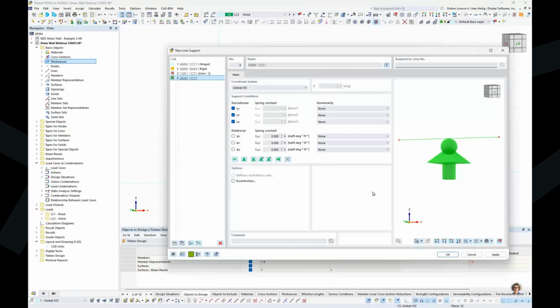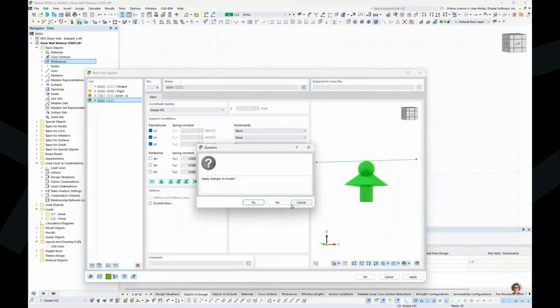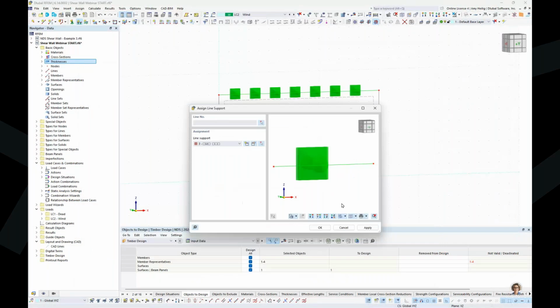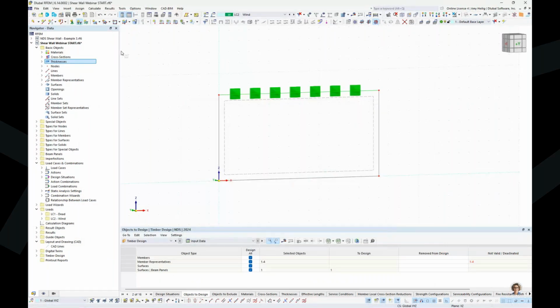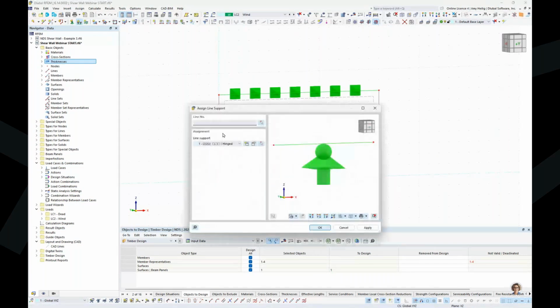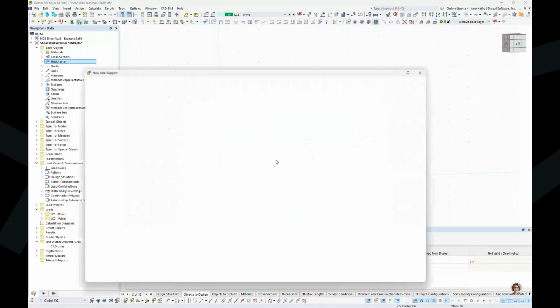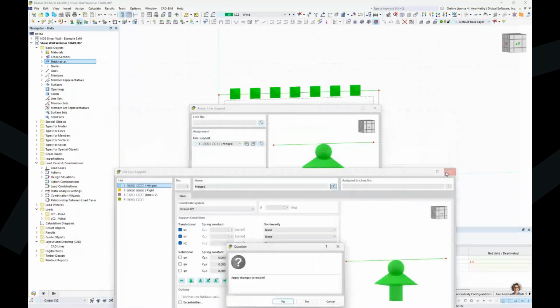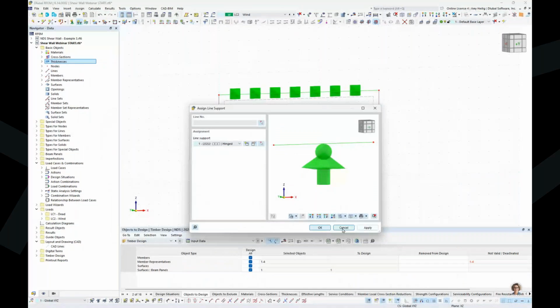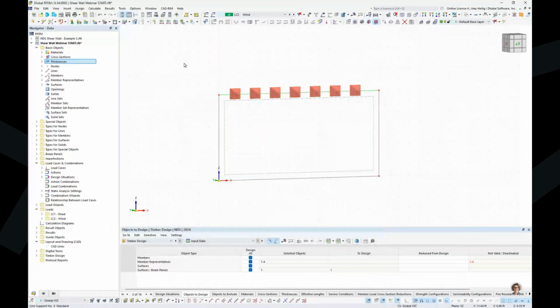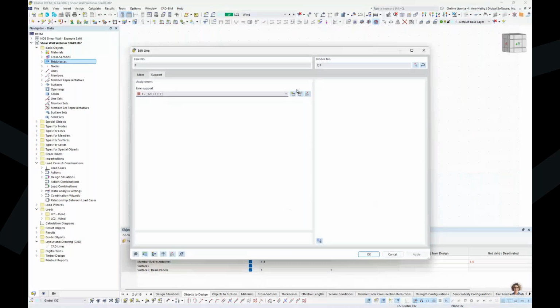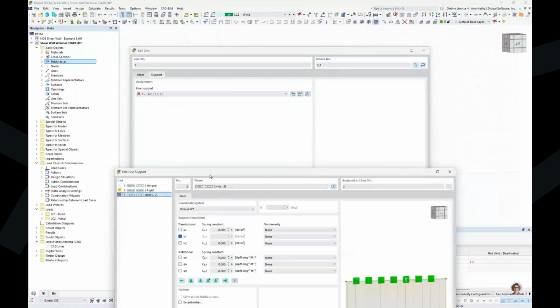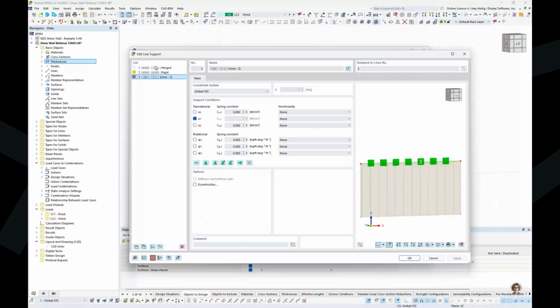And we want to, give me one second, I'm going to actually apply this one to the model. I just want to make sure that that stays. So we'll go back to drawing here a new support type once again, and we create a new support definition type. Oh, I know what I did wrong. I think I did not save here. This one is assigned here to member number 1. I think I went ahead and applied a pinned line support to all of them. So no problem. We can go ahead and graphically select this, and the line support looks good there. Okay, so everything looks fine.